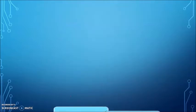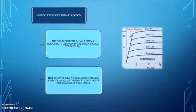First of all, the ohmic region, also known as the linear region, happens when the drain current ID has a linear response to the changes of the drain source voltage VDS. During this region, the junction field effect transistor, JFET, will act as a voltage-controlled resistor, as the VG equals 0.